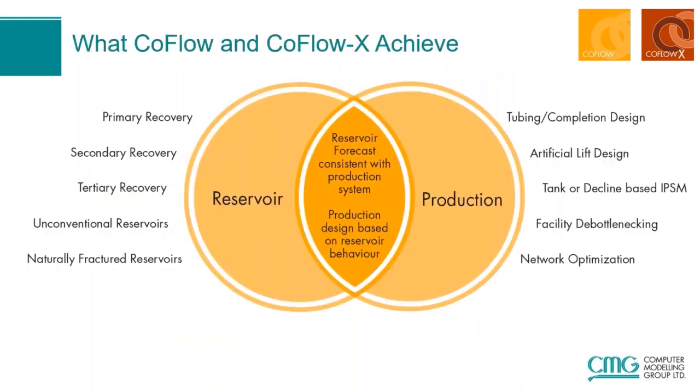So together, what Coflow and Coflow X achieve is that because we are in the CMG world, you have access to IMEX and GEM and Coflow now on the reservoir side. And with that, you can model any recovery process that you can have in your reservoir. Now with Coflow, we also can do production engineering, which is the right-hand side of this picture. You can do tubing completion design, artificial lift assessments, decline-based IPSM, facility debottlenecking, and network optimization.